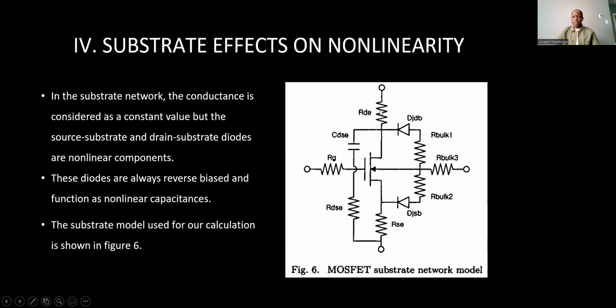Substrate effects on nonlinearity. In the substrate network, the conductance is considered as a constant value, but the source-substrate and drain-substrate diodes are nonlinear components.